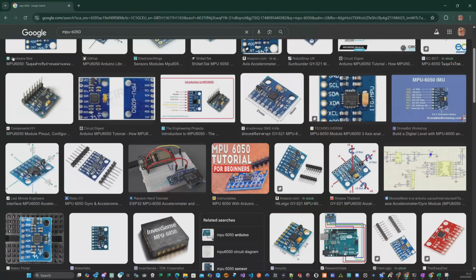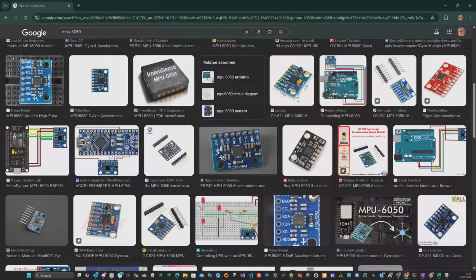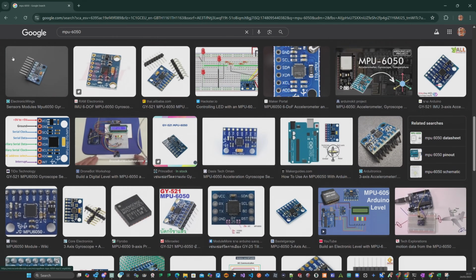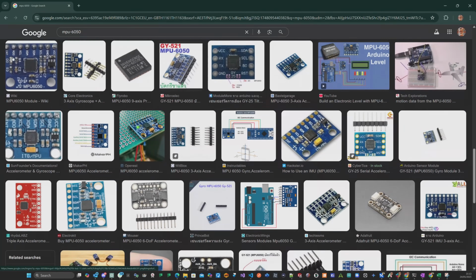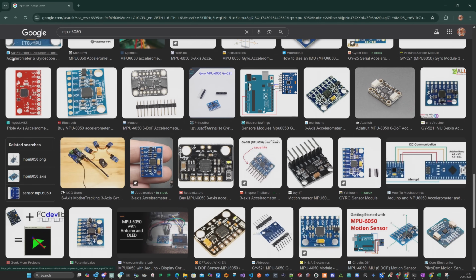The long form of this test will involve dynamically adding weight, and that will change an AI's interaction with its motor neurons, and it's much more complex and long term. It's a story for another day, but for now, what I know that I need is an inertial measurement unit, or an IMU chip, that can detect the movements. I started by looking for a 6-axis IMU that could be easily powered and controlled by an ESP32, and I came across the MPU 6050 module.